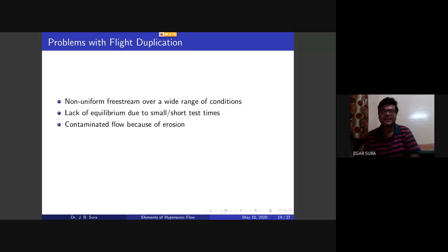That means the cross-sectional area of the nozzle changes, and very small particles, micron size or maybe nanometer size, metal particles fly with the air, which will change the property of the flow finally. If it hits one sensor, it will give you a higher reading every time, not necessarily the same case.